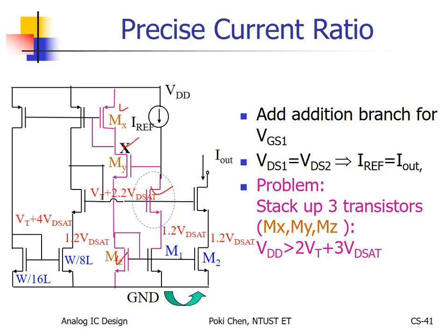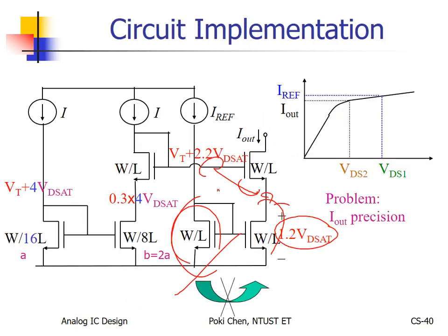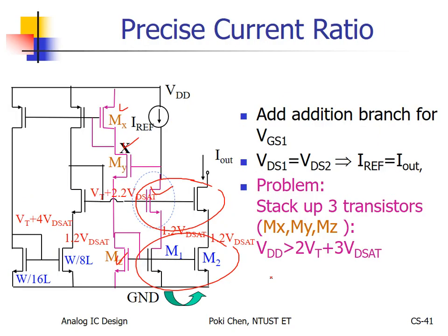For the main transistors and cascoding transistors, they don't generate the bias by themselves. Here it generates the bias by itself, then they won't be matched. So the solution is to support the current controlling transistors and cascoding transistors with biases generated by the others. That's it. Piece of cake.